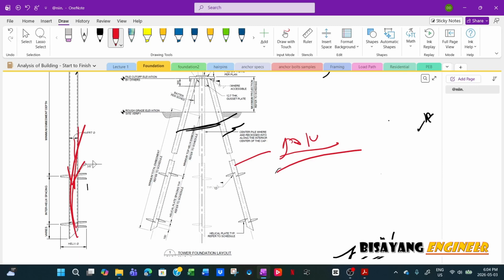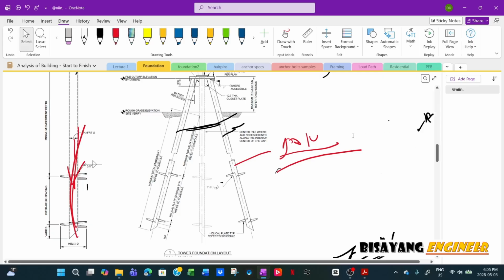It depends on how many years you intend to use this, or the lifespan of the building, and then on how many micrometers per year of corrosion, which depends on how corrosive the environment is. If you are in a marine environment, I don't think it's recommended. You can still use it, no one would prevent you from using it, but you really have to account for the corrosion.